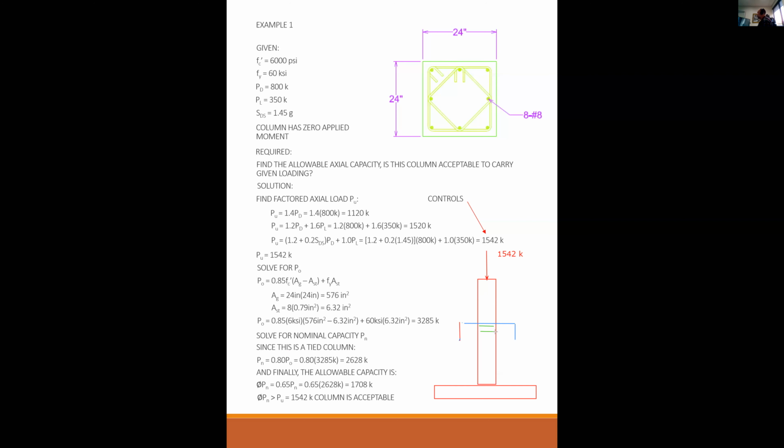And they're at a certain spacing, like so. They have no bearing on the capacity of the column directly. So the green ties that I showed here are really just for completeness of what this thing would look like. But these ties do not add to the capacity of the column directly at all. What does add are the green dots.